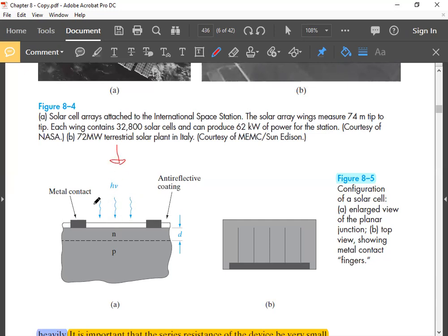So obviously you can understand light will penetrate this surface, will go into the depletion layer or close to the depletion layer of this PN junction, and will generate optically generated carriers, excess carriers, and those carriers will take part in the current conduction, which gives actually the IOP, optically generated current, from N to P, right?